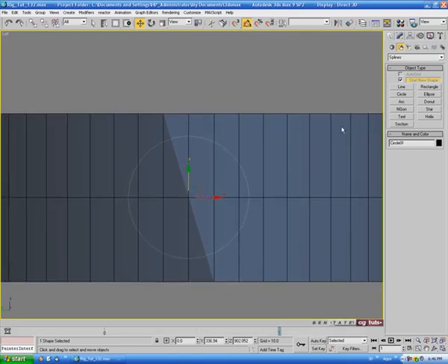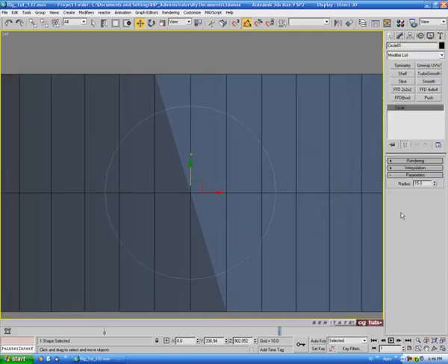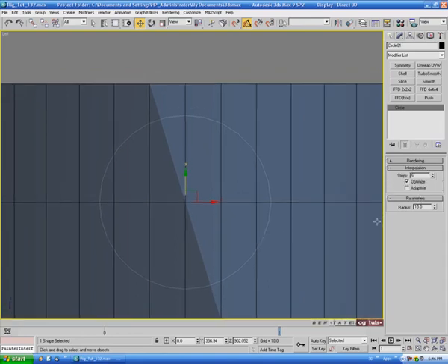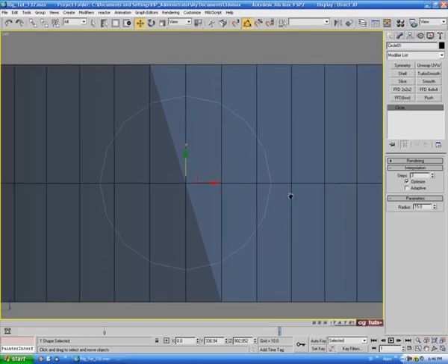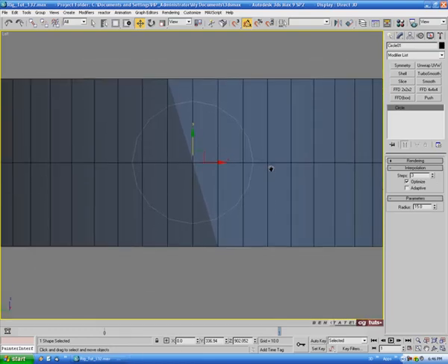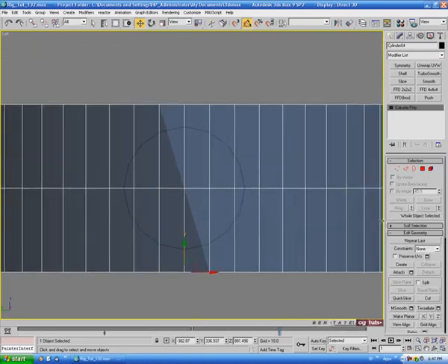And we're going to need to kind of cut the shape of this into the cylinder the same way as we did earlier, but we're going to need to add some more sections on the spline here. 8 won't work for this. Okay, so I'm going to take the steps down. Okay, we're going to have to take it up a little higher. Let's do maybe 3 on the steps here. And that'll give us a 16-sided circle, which should work here. Alright, so we'll reselect our cylinder piece.